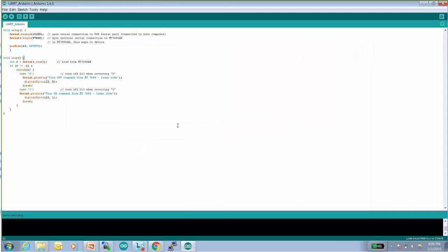Now, how do you run the Arduino Yun Bridge Library example? Once you put the board in Yun Bridge activated mode, you can directly run any Yun Bridge sketch. So you don't have to have Python. It's purely Arduino-based programming you can use here. So how do you do that?